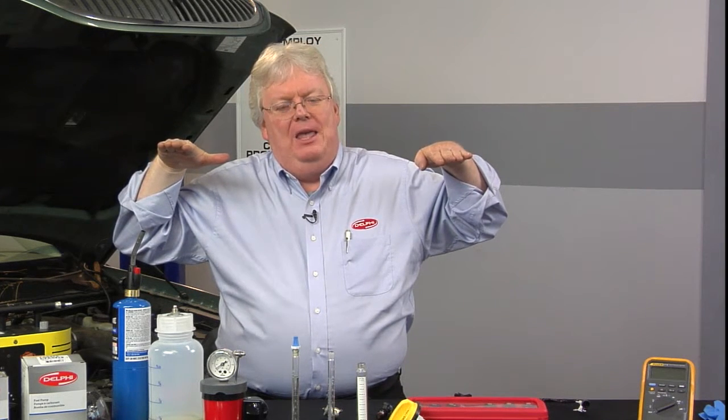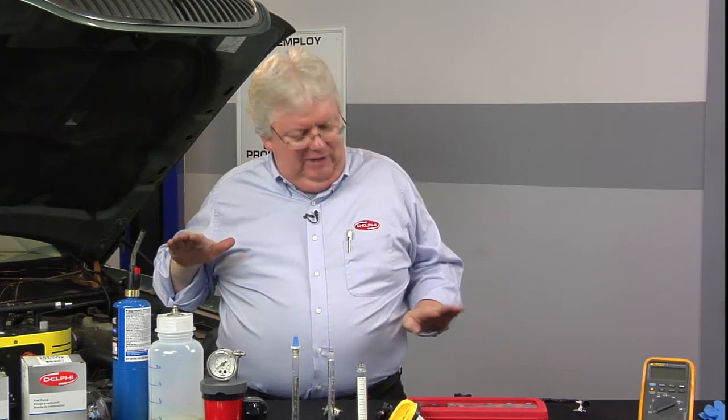So lambda and air fuel ratio are essentially the same. One lambda is 14.7 to 1. 1.1 or 1.2 lambda, higher than 1, is a higher air fuel ratio, 16 to 1, 15 to 1, higher than stoic. Less than stoic, 12 to 1, is less than 1 lambda. It's 0.7, 0.8, 0.9 lambda. So when you see the mixture go lower than 1 lambda, lower than 14.7, that's rich.